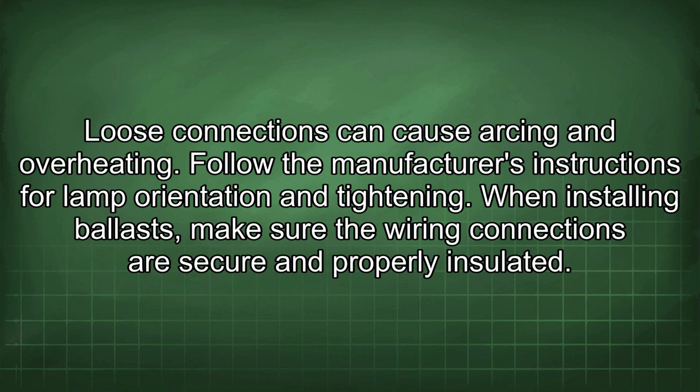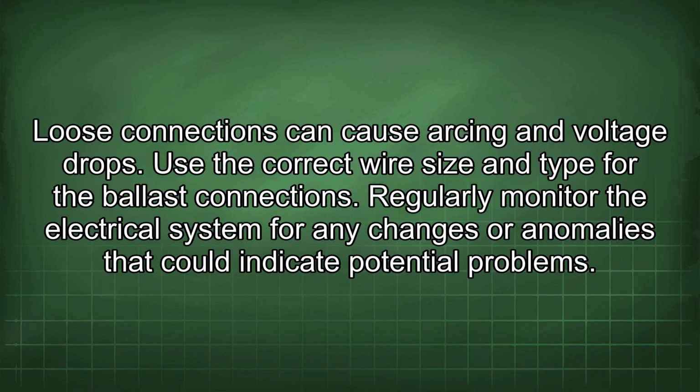When installing ballasts, make sure the wiring connections are secure and properly insulated. Loose connections can cause arcing and voltage drops. Use the correct wire size and type for the ballast connections.